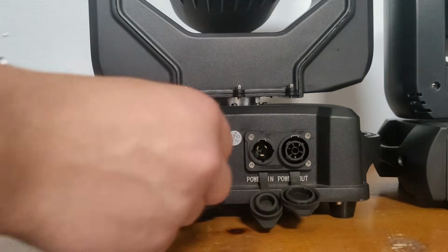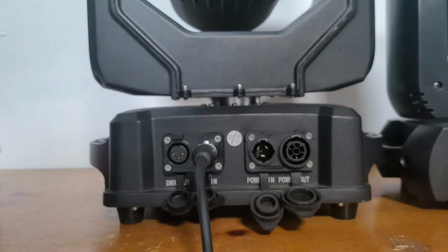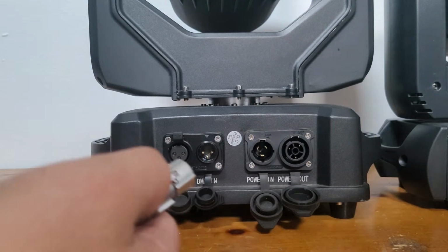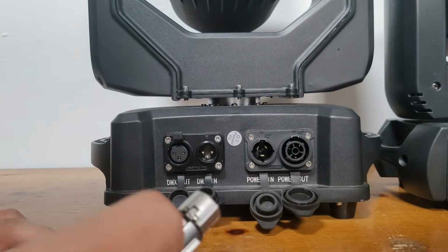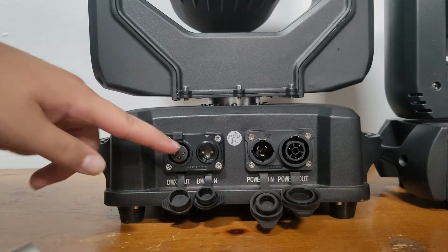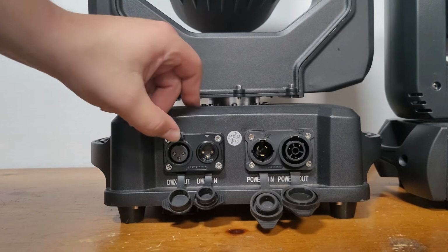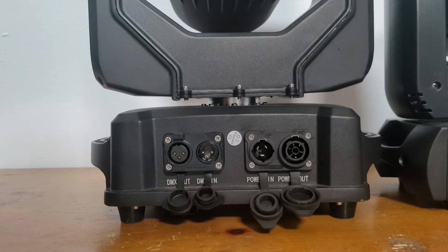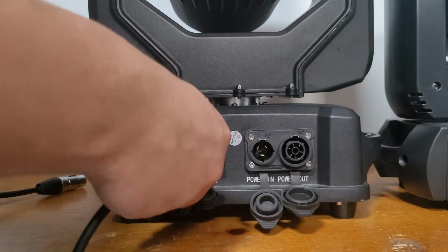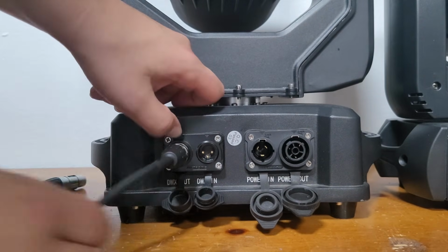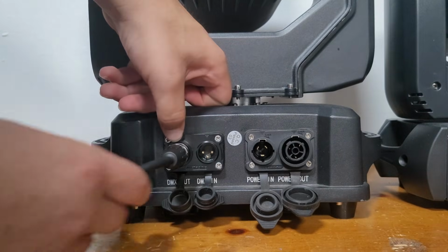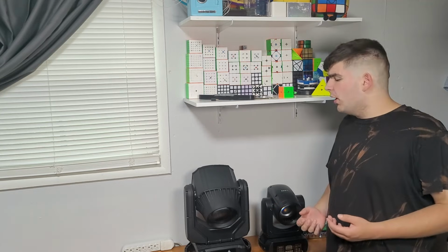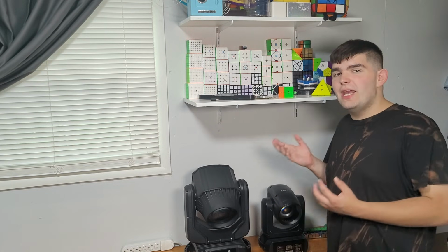And DMX connectors, they just simply plug right in, like that. And on the female side, there'll always be a little button or thing to pull on to unlock it. And since this is the female side on the moving head, this is the little button you push to unlock it here. So if I plug in this side of the cable, it is going to lock in. And the way to pull it out is push this button up here, and then I can pull the cable out.